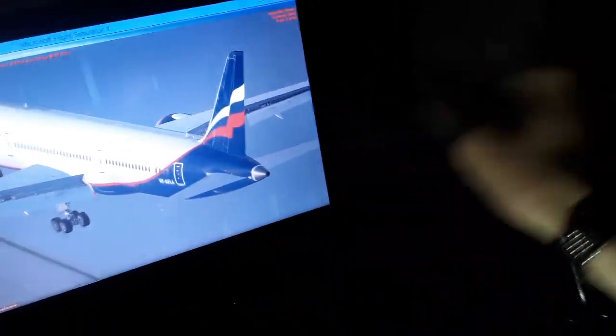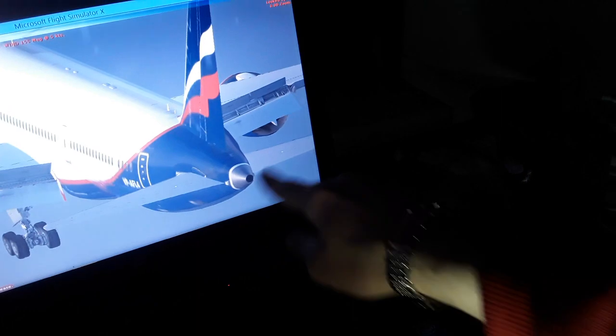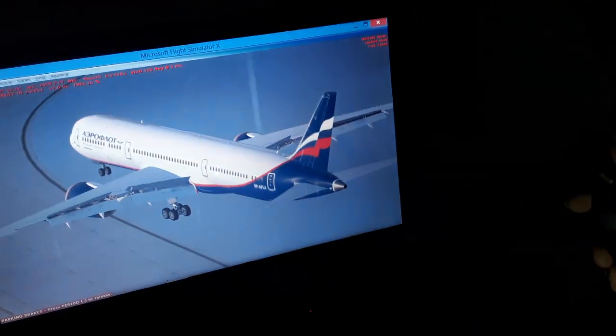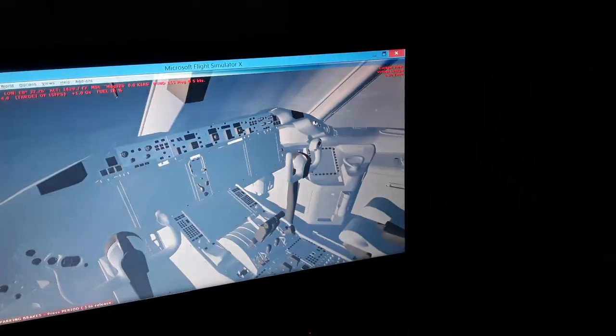And you have also the alternate trim channel, and you have the automatic trim, so you can trim the horizontal tail elevator in flight. You can see this surface move using the side stick or the yoke. You have also the trim switch inside the cockpit of the Boeing 787, so you can also trim manually. And you have the automatic trim for this surface. On some aircraft it is the whole elevator that is trimmed up and down,